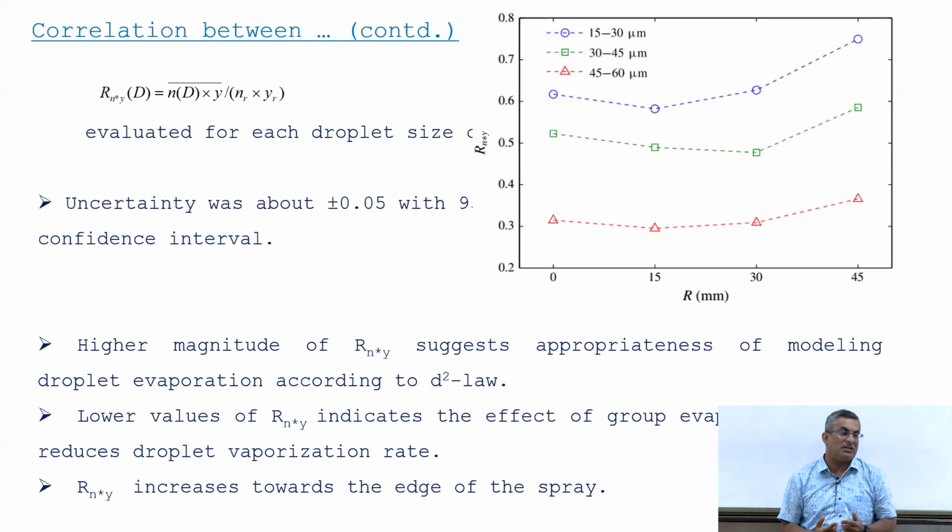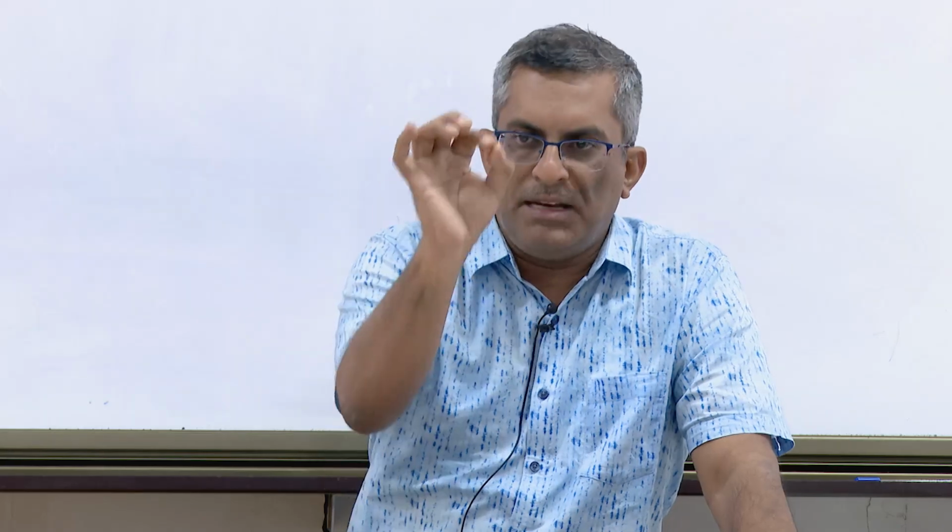It depends on the density of the vapor itself. Should the vapor density be equal to the air density? If yes, then they will move at the same speed. And the other factor which governs this is the local vapor mass fraction. So, finally, the gas velocity at any point of time is a weighted average of the velocity of the vapor and that of the air.